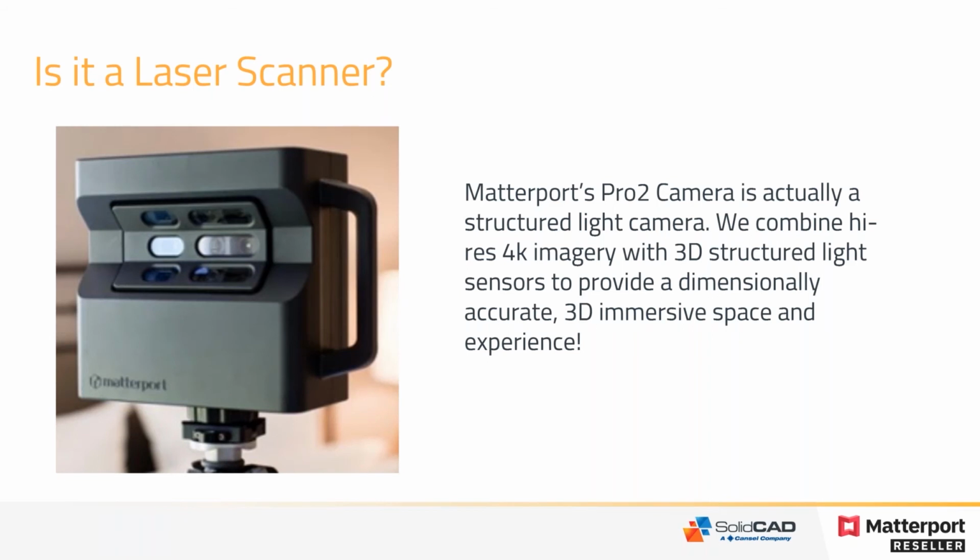I just want to emphasize that a very common question I get is, is it laser? It's not a laser scanner. It is a photo-based scanner with a structured light sensor in it. So it is using infrared light to create meshes, kind of similar to the Microsoft Xbox Kinect, but it's capturing that mesh texture surface of the interior, which, using the Matterport cloud plan, will allow you to convert that into a decimated point cloud that we would import into our Autodesk software.